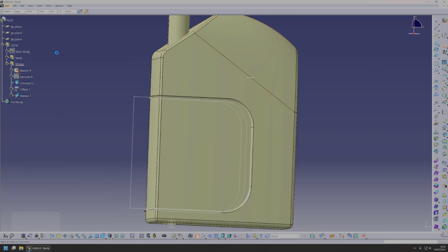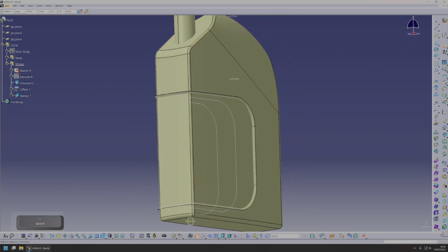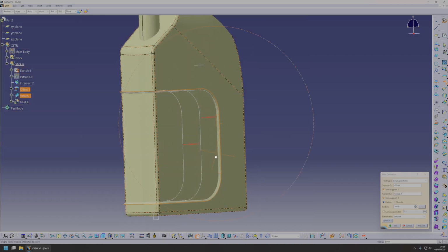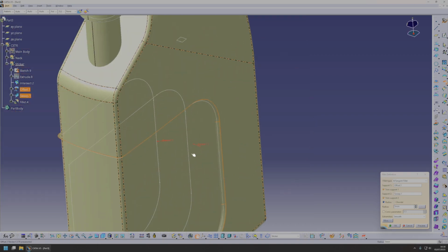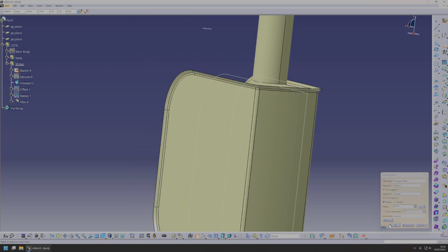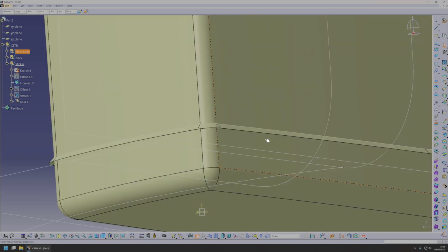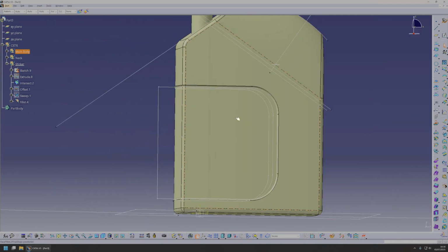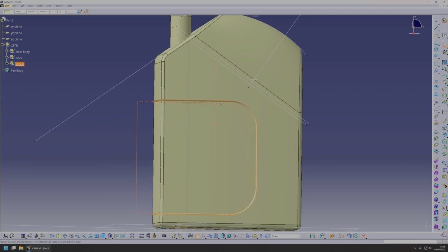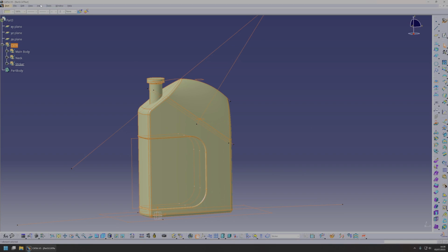Great, now go ahead and hide the main body for a little bit. We create a fillet between these two. 5 millimeters. Let's see what's wrong. I guess this was wrong. Yeah. And we're gonna use this at the end to create the indent, but we can just leave it like this and don't worry about it for now. Okay, so the hard part is now closing in.